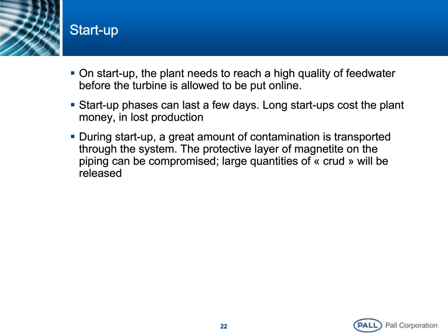Now the problem, during startup, these protective layers of magnetite, in my case here, can be compromised, and therefore a large quantity of particles will be released, and that's what we call the crud burst or crud release. That is why high efficiency filtration is critical to a proper startup, because you want to avoid the consequences of this magnetite layer just basically dumping into the water and starting to be carried through the system.